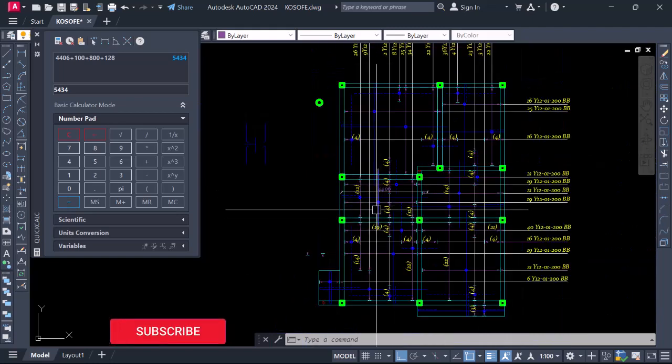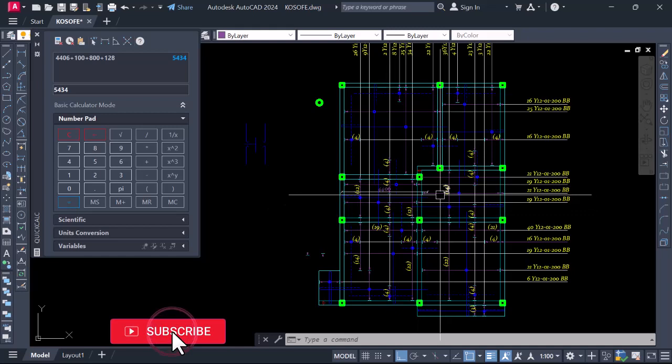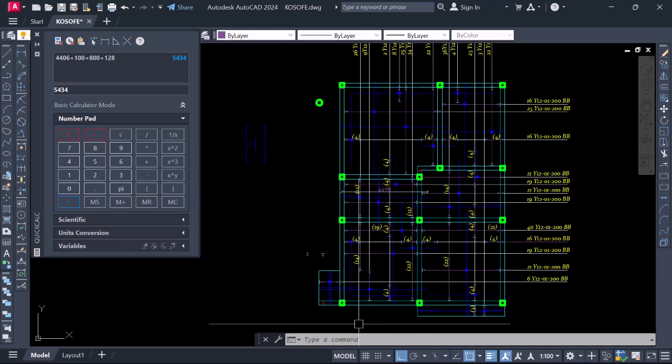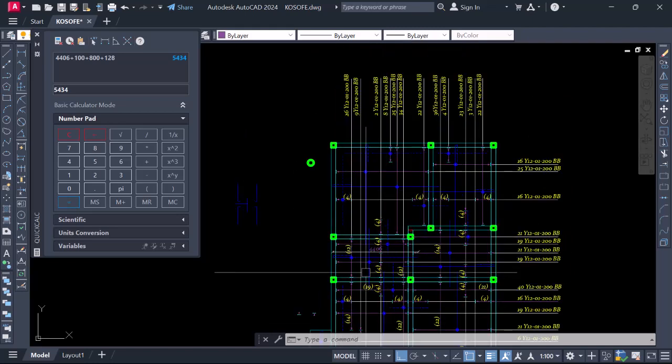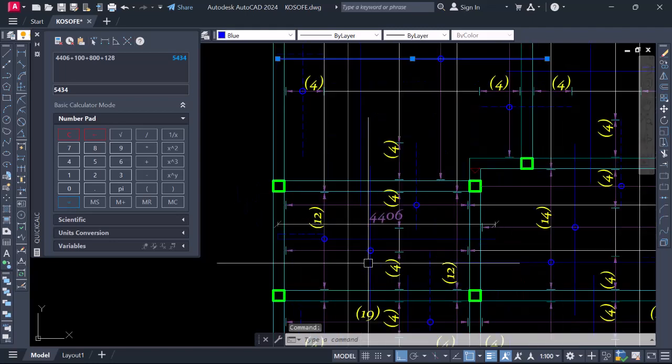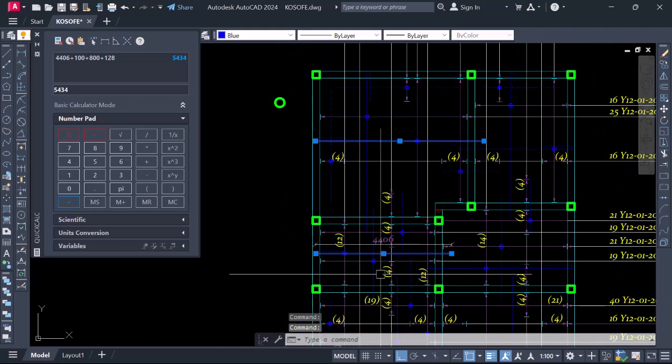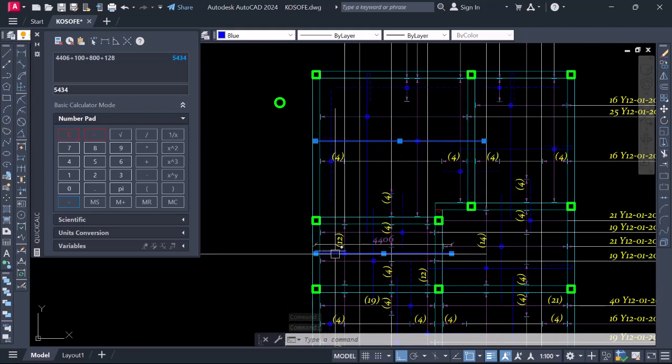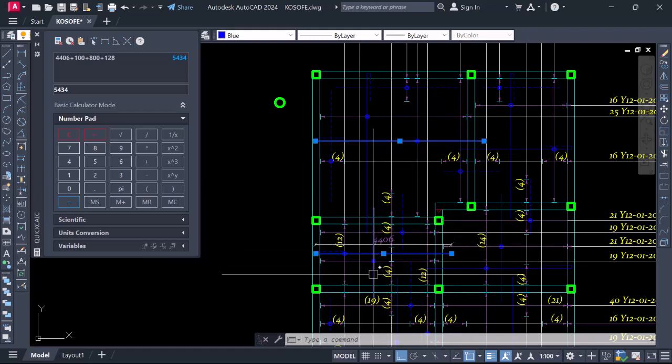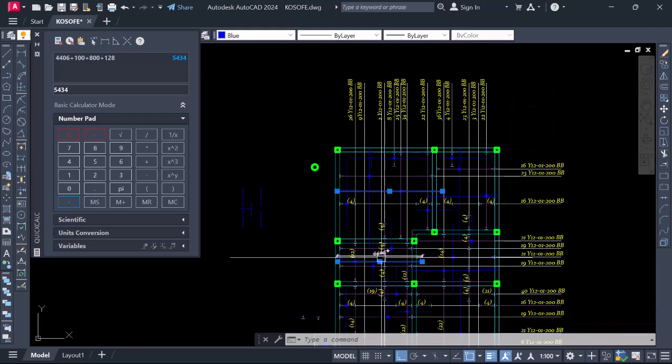Okay, so the question is, do I have every other reinforcement that have the same length as this? Which the answer is what? No, I don't have similar reinforcement in this slab as this. Because you can see this other reinforcement, the length is different from this other reinforcement. You can see, because this is running through this span. You can see where it terminates. You can see where this reinforcement terminates. So this length in this scenario is going to give us different bar numbers. They're going to have a different bar number.